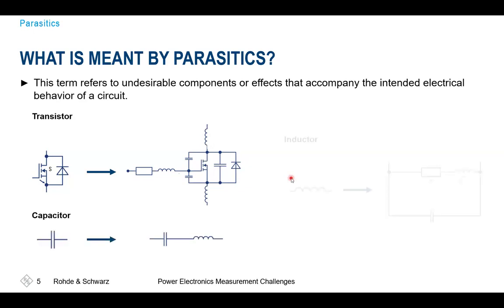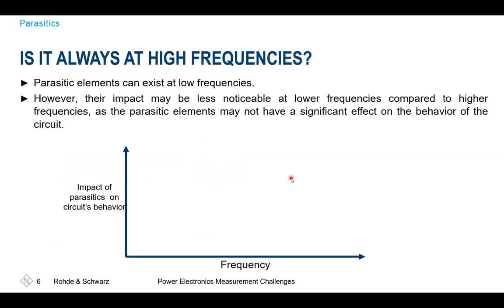of your housing. So basically, everything can be interpreted as an RLC network. And as we all might remember from our studies, we'll have an increasing effect of these parasitics with the frequency. So the faster we are switching, the higher the frequency components induced, the higher will be the effects of these parasitics, and thus also the losses caused by these effects. So with the losses, it's not only the saturation that might occur inside a ferrite material, it's also meant for the general inductors that have other resistances and thus are causing other losses inside the systems as well as the caps.